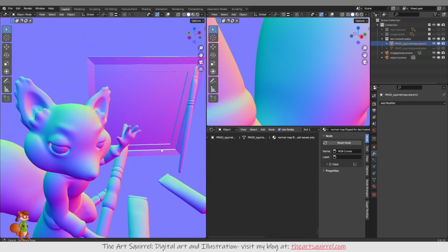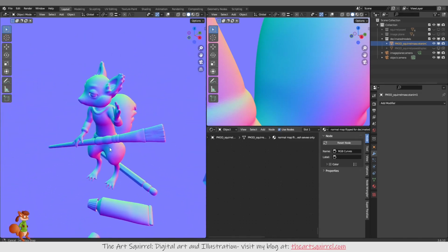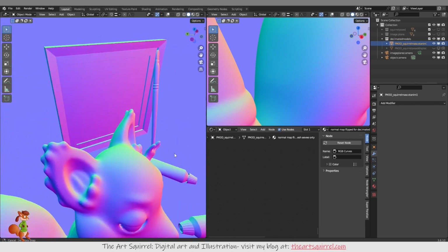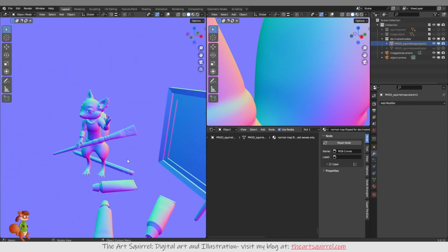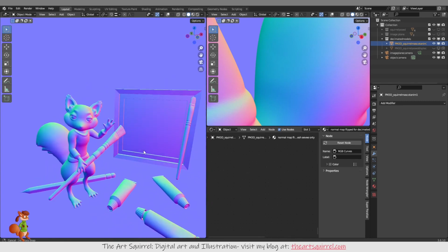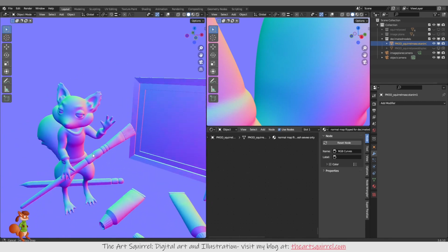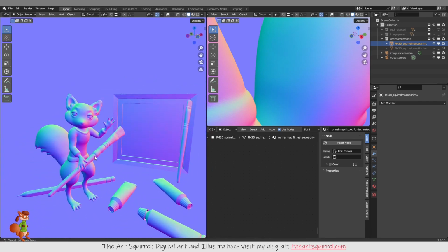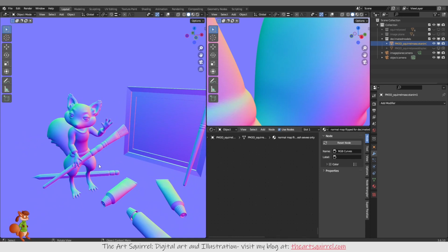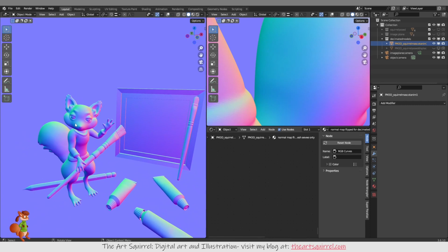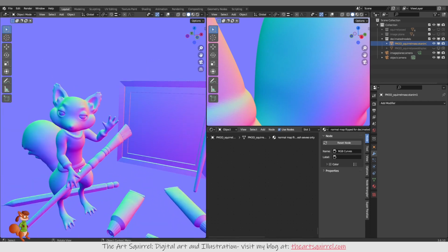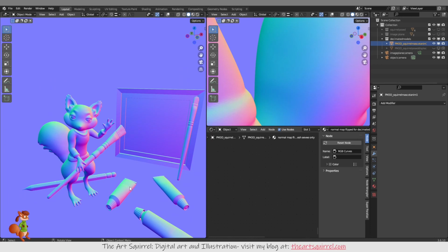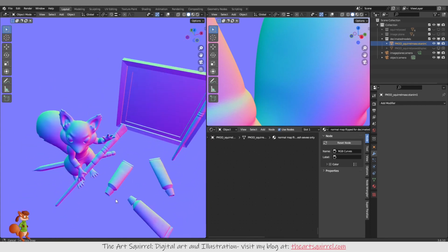I must have combined these objects into this one object, and I did pose him, so I will have used a lower resolution model at some point and then rigged it and posed it, and then I applied a displacement modifier to it to add the details, and then I've exported that, applied the modifiers so that it's all just a posed object.